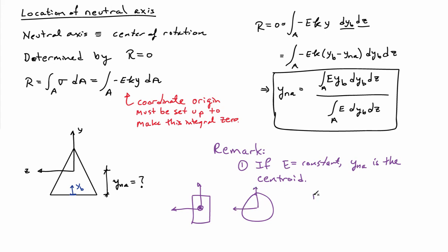But if you have a cross-section that is a bit more complicated, suppose you had a T-section, then the centroid doesn't sit right at the center of the cross-section. It's going to sit at some kind of offset location here. But remember, one of the main results that we had from before when we were looking at statics and calculating centroids is that centroids always sit on lines of symmetry. So if you can identify two lines of symmetry on a cross-section, you always know where the centroid is.